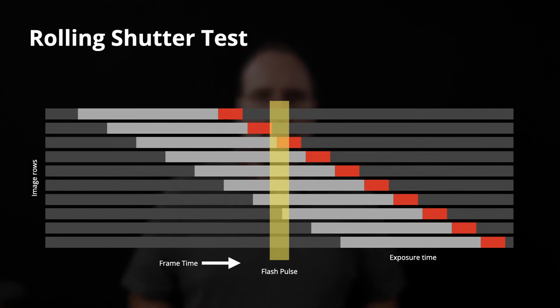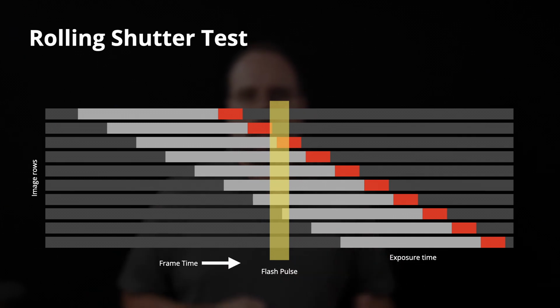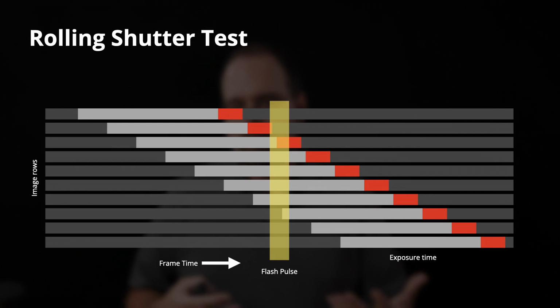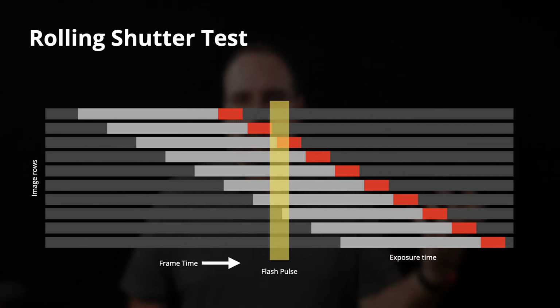So the camera will essentially go through and schedule the release of lines in such a way that it can read out a line before it needs to dispatch the next line, and then as it reads out the sensor, it will basically read out the oldest line and dispatch the next line.